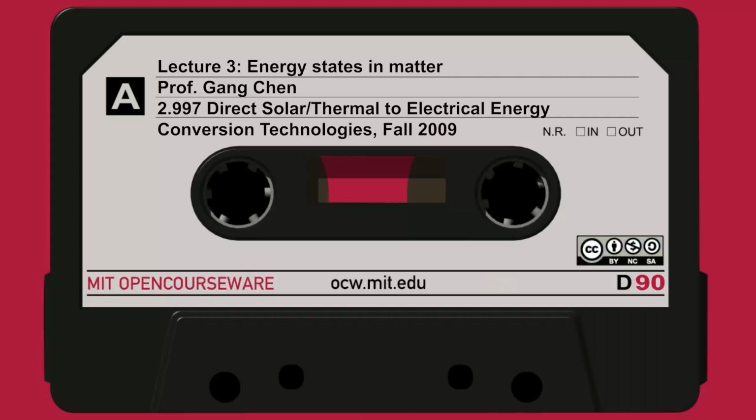So in gallium arsenide, when the photon comes in, if the energy is large enough, you can lift the electron from here to here, and it gets absorbed. But in silicon, because it's an indirect semiconductor, the photon momentum is here, and you cannot lift the electron from here to here. It has enough energy but doesn't have enough momentum.